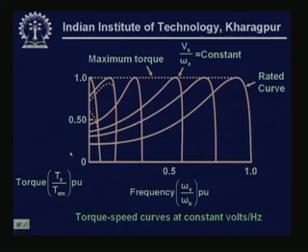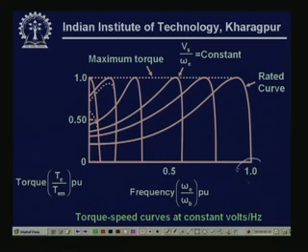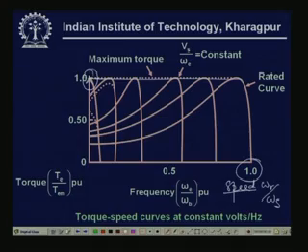So these are the torque speed characteristics. This is speed, omega r by omega s, and this is torque. One thing is interesting, firstly the maximum torque level can be maintained. So even you can achieve a very high starting torque with this control, almost like the maximum torque. So these kind of drives are going to be useful for machines which start on load.